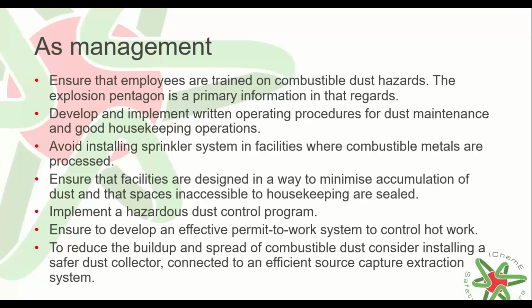Combustible metal dust can react exothermically with water. As such, avoid installing sprinkler systems in facilities where combustible metals are processed. Ensure that facilities are designed in a way to minimize accumulation of dust and that spaces inaccessible to housekeeping are sealed.